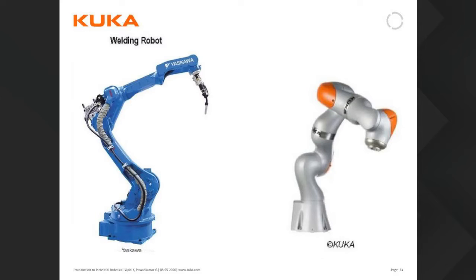So first I will tell what a collaborative robot is. See, when we showed that picture earlier, with the robot there was a human working inside the cell. In that case it can be a problem for the human. That was for teaching. After teaching, the human comes outside and they put the robot into operation. And if somebody enters the room again while the robot is working, the robot will trigger safety and the robot will stop. Why? Because the robot doesn't know if any human enters that place. I'm saying this for industrial robots. It can hit the person and it can be a problem. So we need to take care of safety while designing.